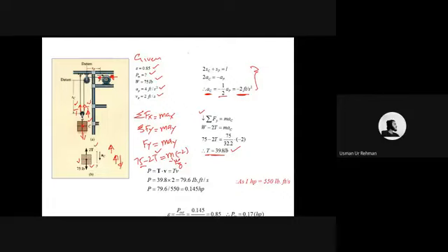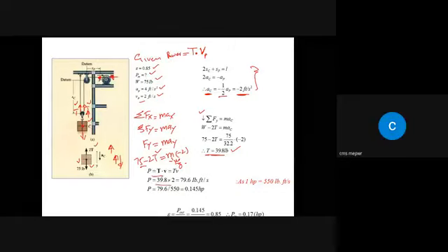39.8 pound. And if I want to find out the power at this point, so I should multiply this force with what? With velocity, right? Yes, sir. Do we have velocity of this point? Yes, sir. Given. Okay, Vp. So can I find out power at this point, right? Yes, sir. So when we do so, हमारे पास क्या आ जाएगा? ये हमारे पास इस इक्वेशन से ये पावर हमारे पास आ जाती है. This is the required power. ठीक है? This power is in foot pound per second.